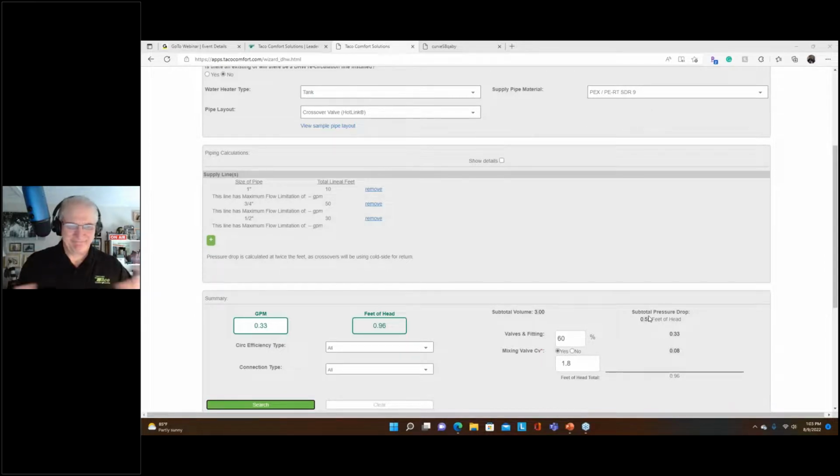So yeah, we're using the cold water line in that application as the return line, but because the hot link valve does its job, it closes that valve once the hot water arrives at the system, and we don't flood the cold water line with hot water, because that would be silly.